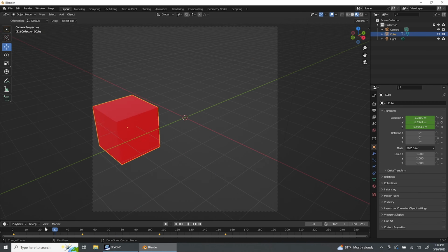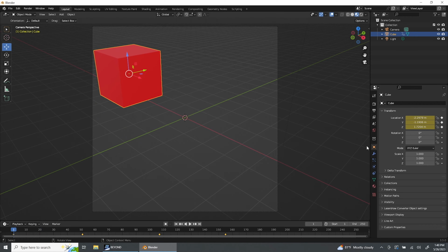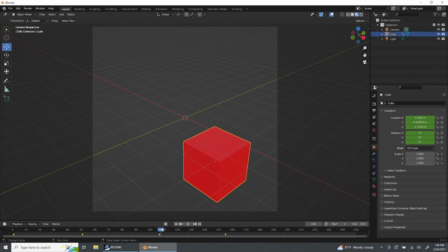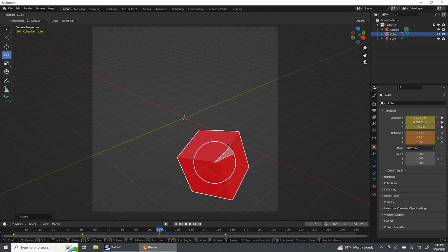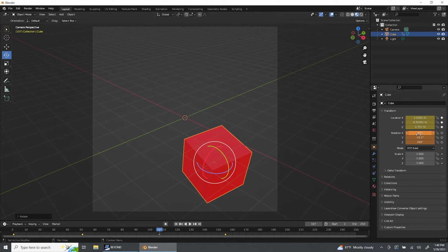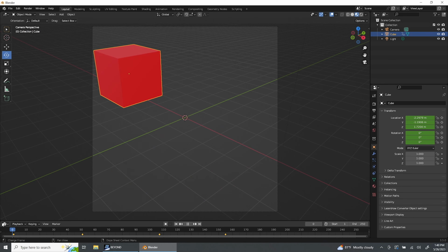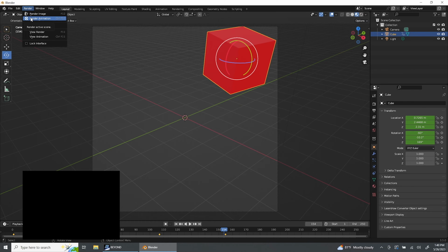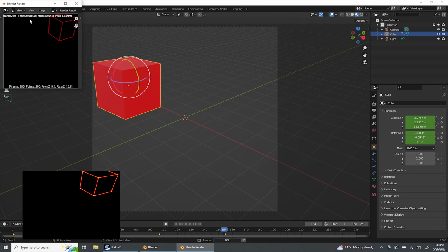Now what I'll do is go back to the original position, and what you can see is now as I move the time slider, we've created a little animation in terms of the position. What I'll do is say I want that to be an initial rotation angle, and maybe come over here and change the rotation angle. And we'll make that a new rotation angle, at this position in time.